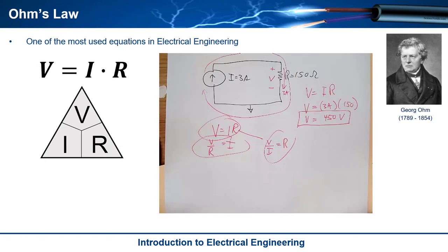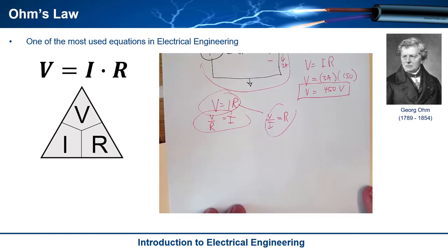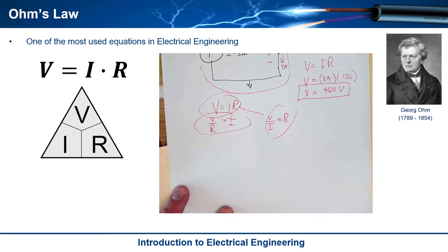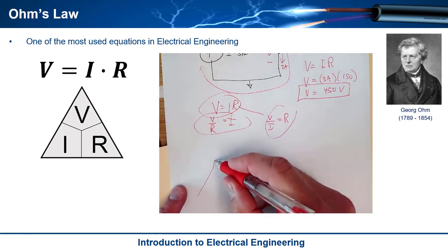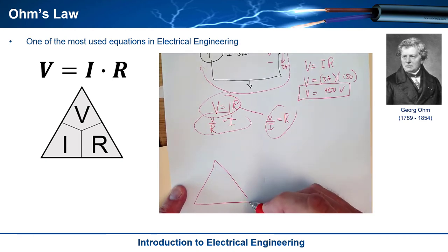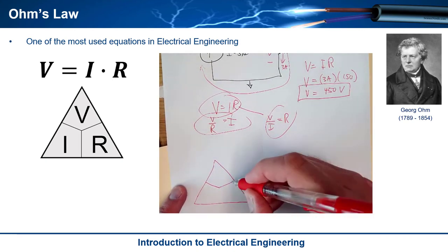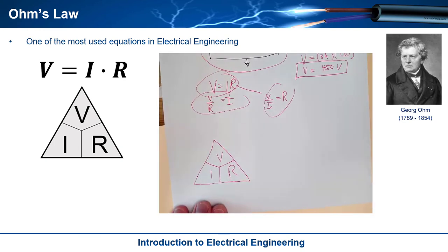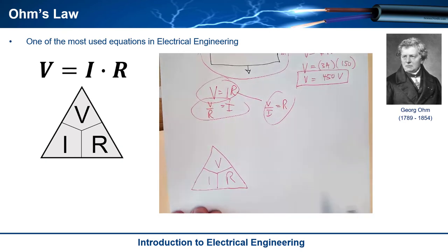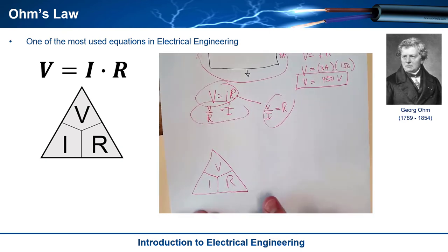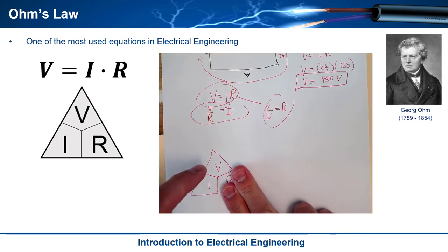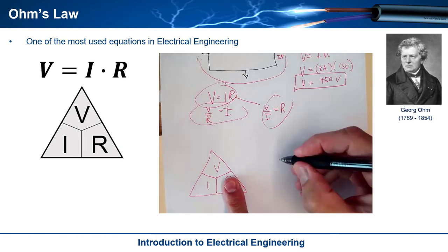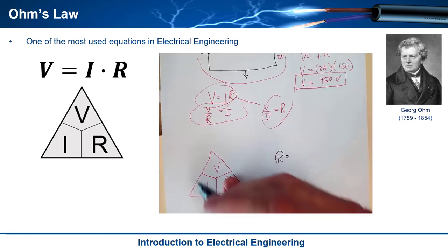And that brings us to one final funny thing. In the beginning, people really didn't like doing algebra, so they came up with this Ohm's Law pyramid that I have here. You have this triangle, and I'll show you how this works. It's V, I, R, and it reminds you of these three equations. If I want to solve for resistance, I can cover what I'm trying to solve for, and it's V over I, because the V is above the I.